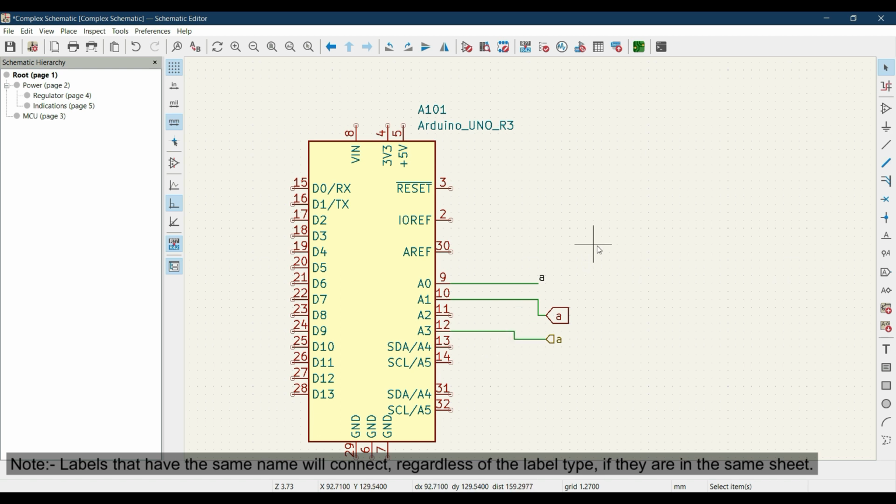So in order to highlight the net, the schematic editor has a tool over here, that is the highlight wires and pins of the net. Once you click on any wire or a pin, this will highlight the entire net, and all the pins that are connected in that net. So let's just click on this.